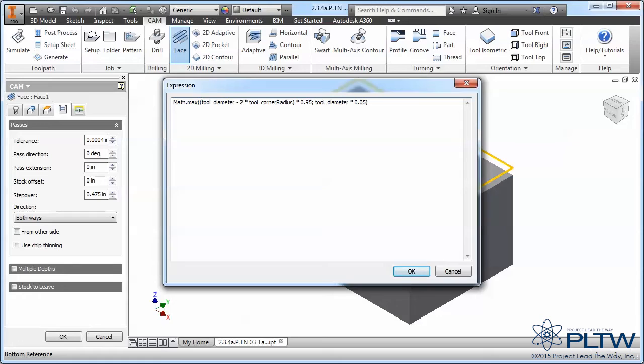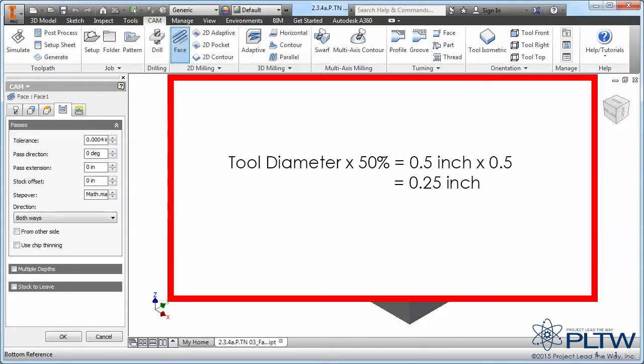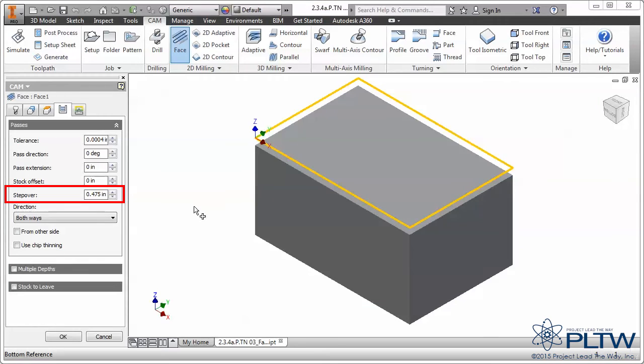This means that 5% of the cutter diameter will overlap the previous pass, resulting in a more efficient stock removal than 0%. A more conservative 50% is recommended to extend tool and machine service life. A 50% step over for this half-inch tool is 0.25 inches.